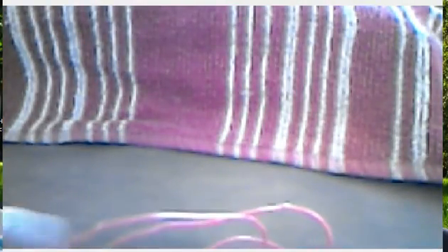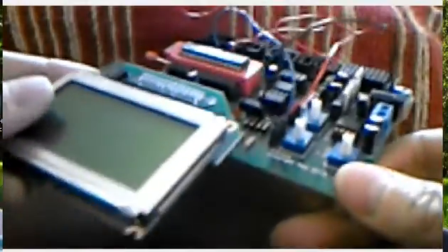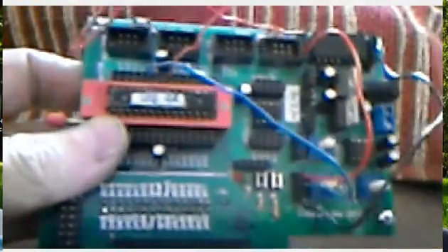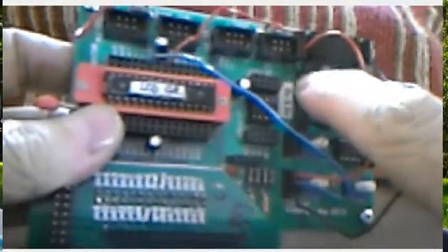Next, let's remove this, and we're going to take a look at what it would look like when you actually have these parts in your hand. So with the equipment that we have, you can see that I have attached a graphic screen to our green board. There's the graphic screen. Notice the adapter. Notice the port that it plugs into. This screen runs off of 5 volts, so we want to make sure that we have the 5 volt jumper selected, which is right over here.